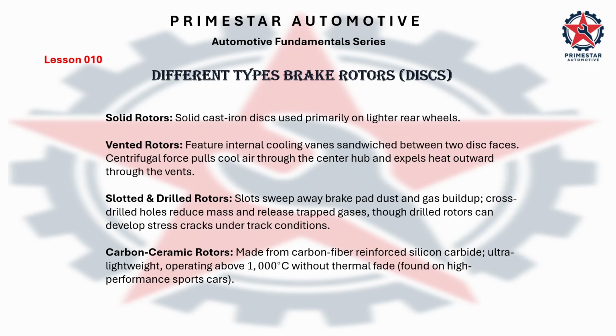Slotted and drilled rotors. Slots sweep away brake pad dust and gas buildups. Cross-drilled holes reduce mass and release trapped gases. Through drilled rotors can develop stress cracks under track conditions. Carbon ceramic rotors, made from carbon fiber reinforced silicon carbide, are ultra lightweight, operating above 1000 Celsius without thermal fade, found on high-performance sports cars.